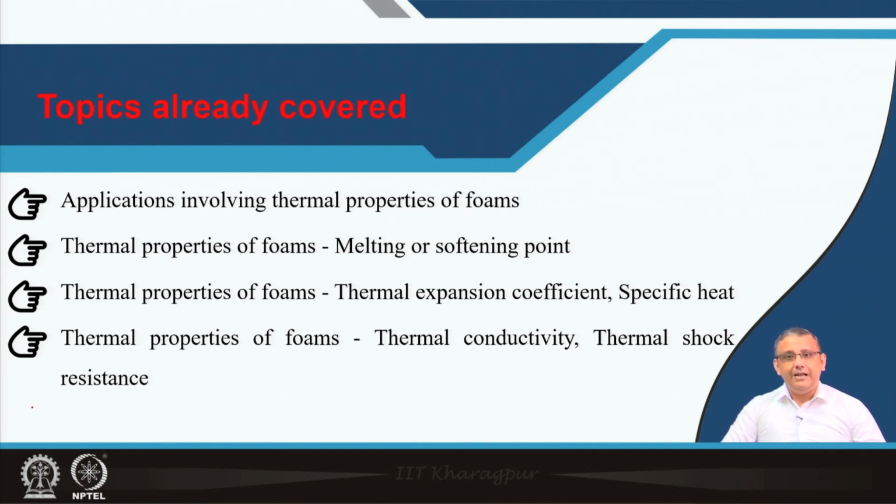There we learnt that both melting point and expansion coefficient are actually porosity independent. That means they do not depend upon the amount of porosity, and these values are similar or identical to the properties of the bulk material of which the foam or cellular solid is made.